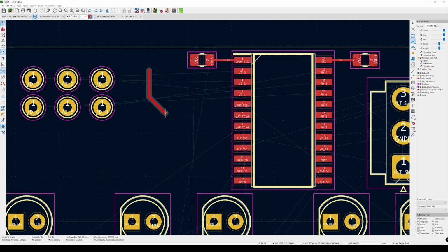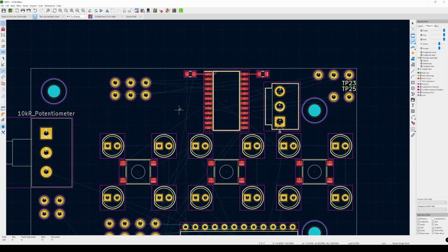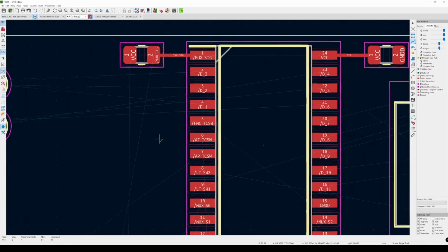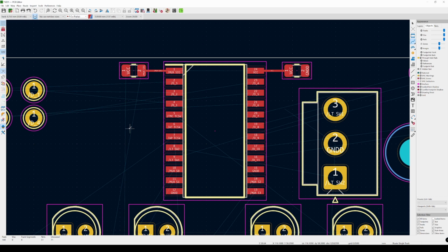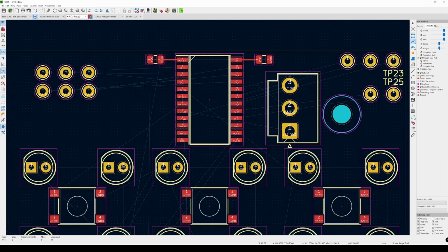And on the settings menu you can adjust that clearance, but the one that KiCAD has automatically set is, in my opinion, just fine for what we are doing on these not so precise PCBs. I would imagine, but I'm not exactly sure, bigger clearance is more safety margin, less interference on the lines, but the default clearance should be fine.